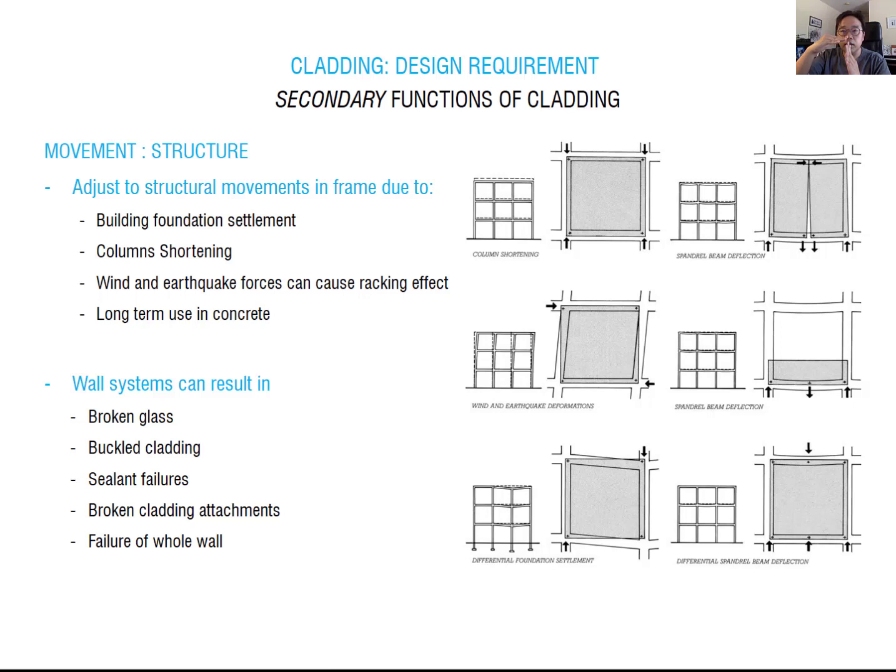The most important thing is that when you keep pushing it, the gap between the cladding and the joint keeps getting bigger and bigger. When you have a bigger air gap, water comes in, also moisture transfer, and lots of different issues between the cladding and the structure system.